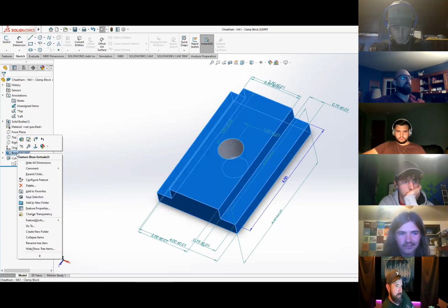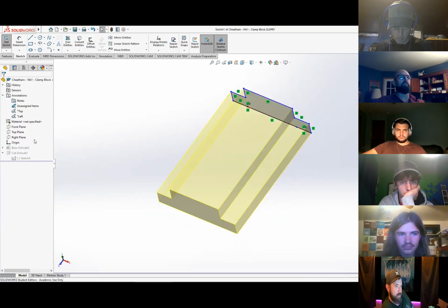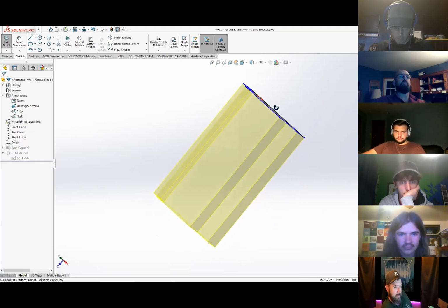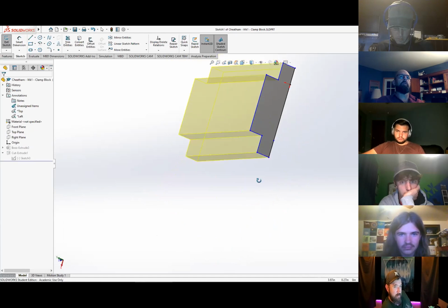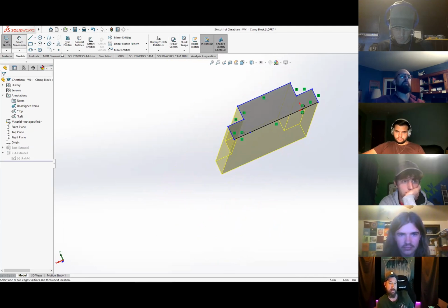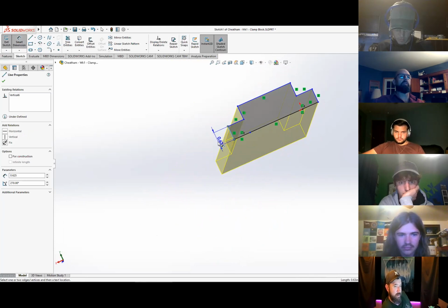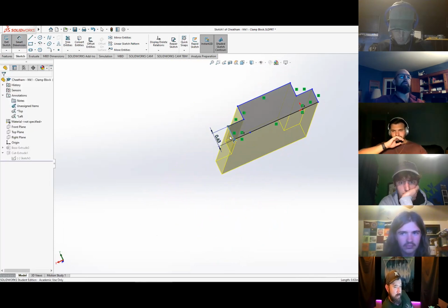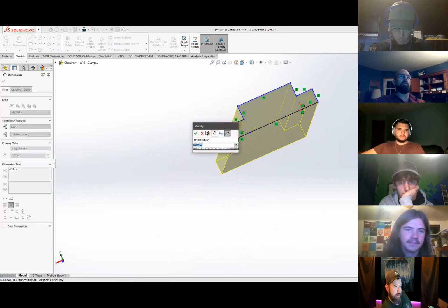I'm going to edit your sketch. Here's your very first sketch, and you were dimensioning it afterwards. This is what you want to dimension, is your sketch. See? So here you would dimension each sketch, and before you go on to the next sketch, you dimension it.